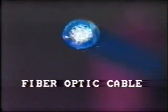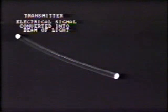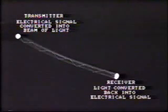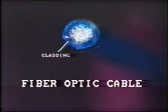In this arrangement, the signal is transmitted by light waves traveling through an optical fiber. The fiber is made of non-conducting material, so it cannot provide a path for electrical signals. At the transmitting end, the electrical signal, perhaps a tripping signal from a relay, is converted into a beam of light. This travels down the fiber like this. The signal is able to travel around bends, providing they are not too acute. At the receiving end, the light beam is converted back into an electrical signal to initiate action, say tripping of a breaker. Obviously, the inner surface of the fiber has to be reflective, and its surrounding cladding is specially made to prevent or at least reduce loss of light.